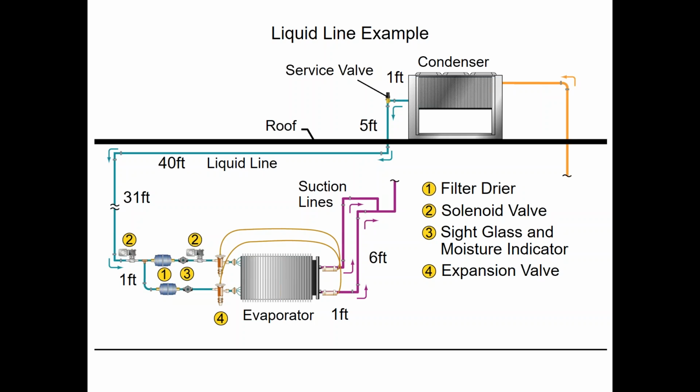No, it's a different animal. The scroll compressors are in our split system condensing units, typically, and in our smaller chillers. They have an oil charge in them, but it's a small oil charge, in some cases less than 64 ounces. So there's not a lot of available oil there to be out in circulation, and that's why we have to eliminate traps.